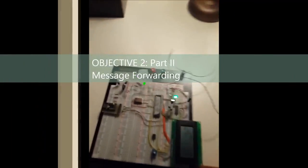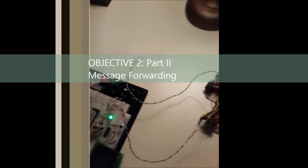Okay, so in this demonstration I'll reset the base station. So basically I'm demonstrating the ability of mote 2 to route data through mote 1 to the base station. Now I've placed mote 2 far over there in the distance, and he can't see the base station from there. However, he could see mote 1, and mote 1 could see the base station.